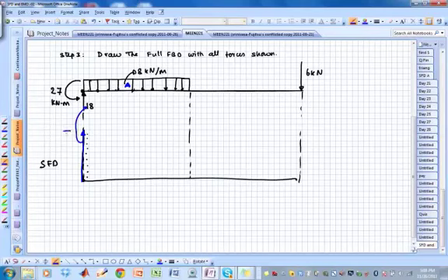If I compute the area of this, area will be 8 times 1.5, that is 12. So what I mean is, after 18, I have to come down 12. That means I'm left with 6. That's up to this point. That is 12, that's the area. So I'm going to go down like a straight line like that.